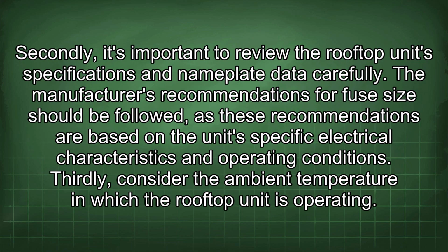Secondly, it's important to review the rooftop unit specifications and nameplate data carefully. The manufacturer's recommendations for fuse size should be followed, as these recommendations are based on the unit's specific electrical characteristics and operating conditions. Thirdly, consider the ambient temperature in which the rooftop unit is operating.